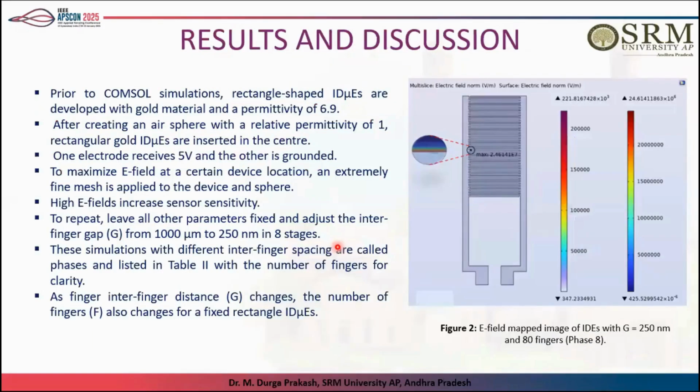And then the design parameters we have taken are relevant towards biosensing applications. Particularly, we have simulated the sensing parameters that we required, by simulating different designs for different dimensional parameters using the COMSOL simulation software. And then finally, we have achieved the sensing parameters we required, what sensitivity and what resolution is required. Accordingly, we changed different parameters in such a way that we achieved the required sensing parameters.